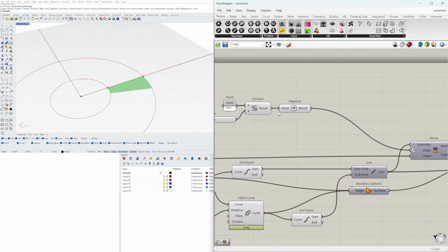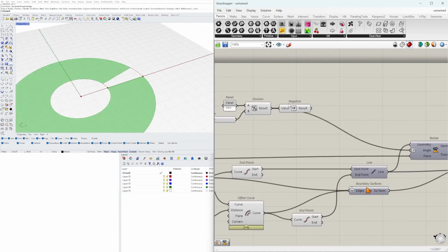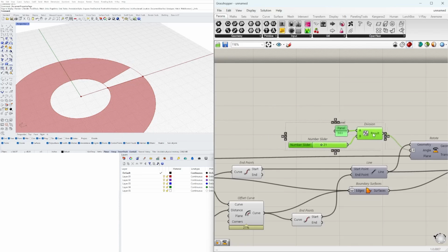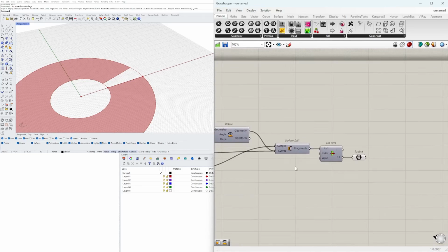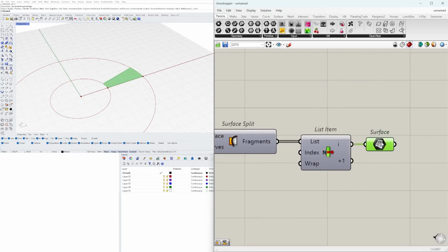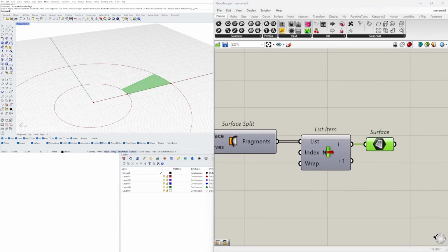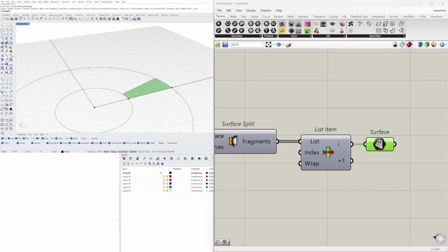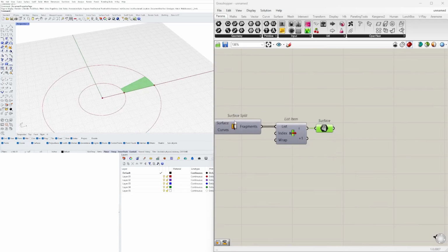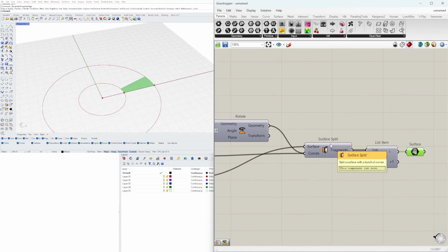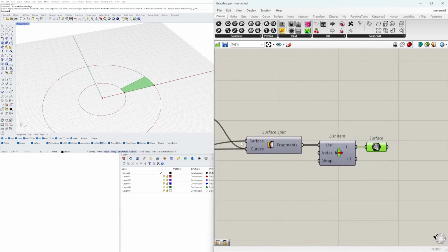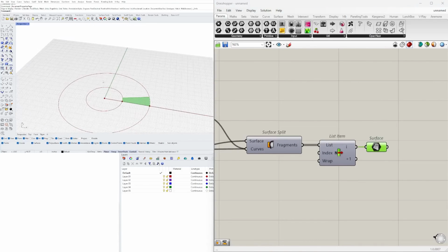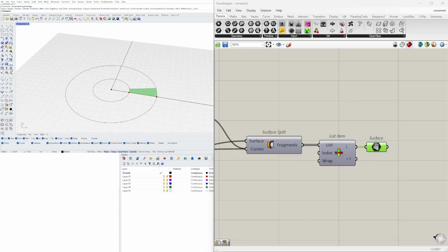Now here, I do have it as a negative. I do actually want it to be a positive. And when that happens, you'll see that the way that this was organized, you actually want to go to this one. So the reason why I do this is it's better to start here and go up and around, just because this is our plus sign, and we just kind of want to go this way. Just understand that there are different ways that we can approach this. So with this tread, let's create the array all the way around to match the circle.